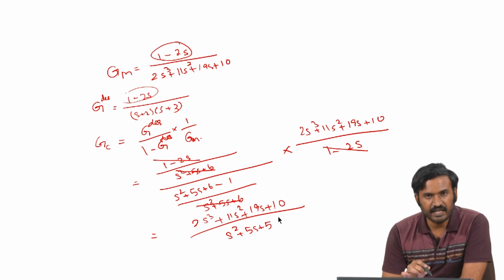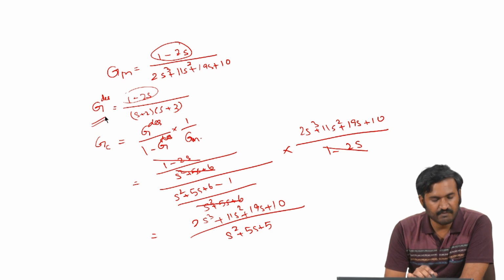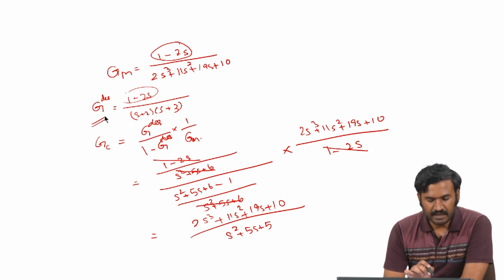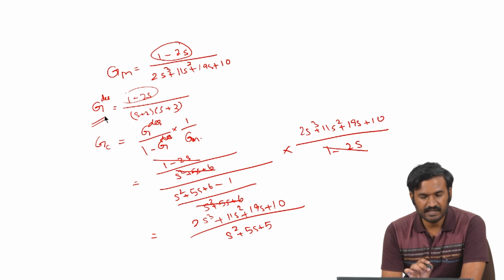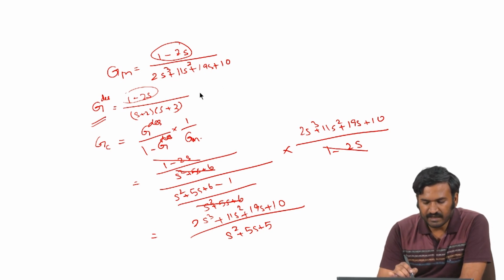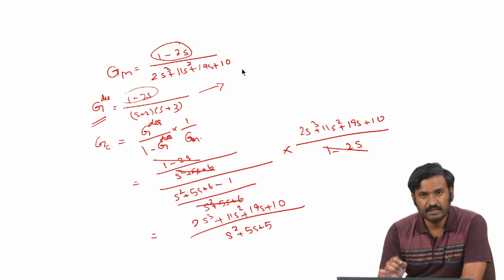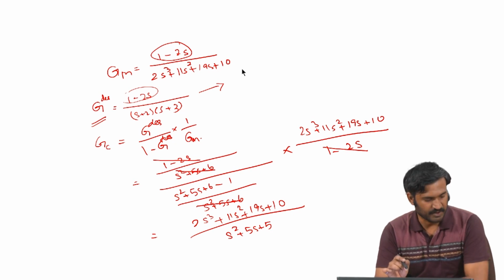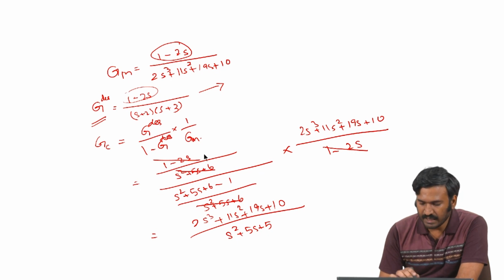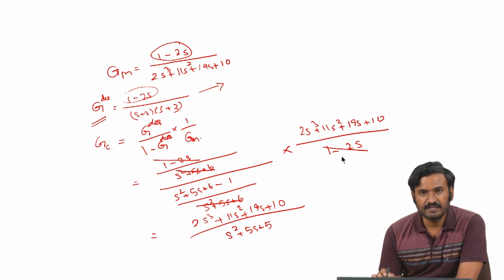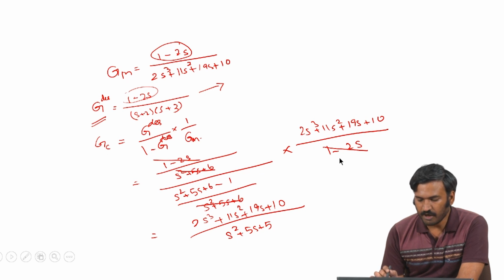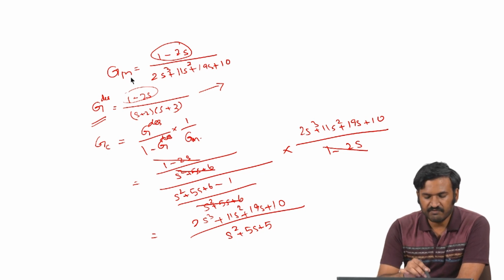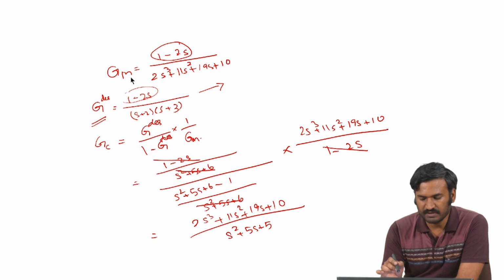Now, we can specify any G desired as we want. So, the main criteria with which we specify G desired is that the gain of the closed loop transfer function has to be close to 1 and the time constant tau of the closed loop transfer function has to be as small as possible. So, remember there is a pole and a zero cancellation here. This introduces a problem when we have a Gm which is not similar to the process we are implementing the controller on.